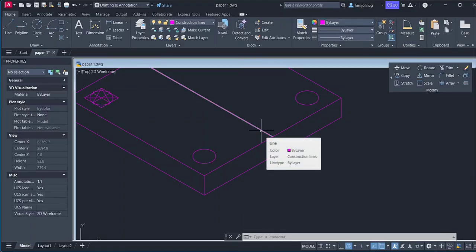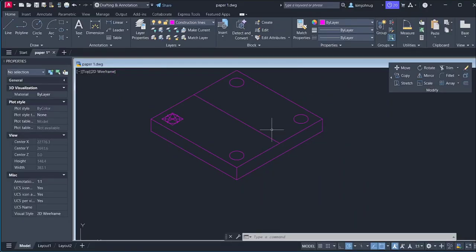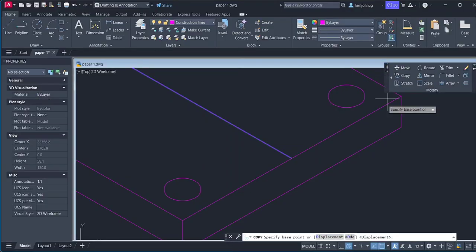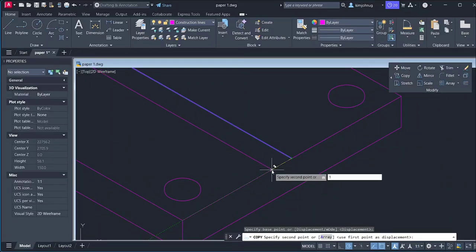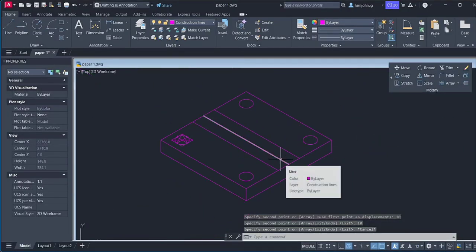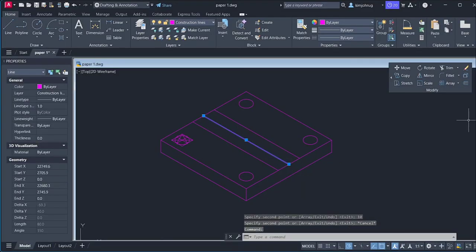I tried to offset, but I think offsets go along the verticals. So what can I do? I can just copy this line through that, and through this I measure 10, right? Then do the same thing this side. Through this I measure 10. So I've copied that distance, and I don't think I need the center line anymore. And remove this.